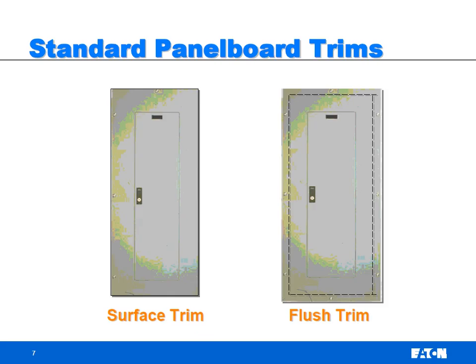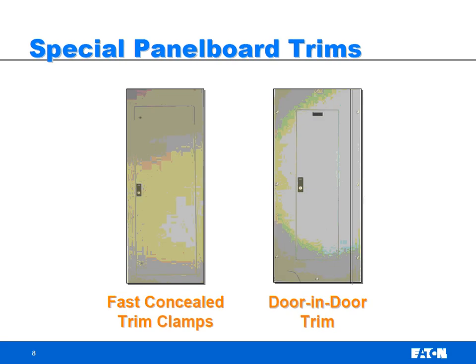Well, if you've got screws that you have to put in, and maybe you've got 8 screws per panel, maybe you can get away with putting in half as many, but it's going to take you 5-10 minutes to put a trim back on so you can walk down to your light, make sure your light works, check your circuit, come back, take off the trim again, do your next breaker, and it can be a very tedious situation.